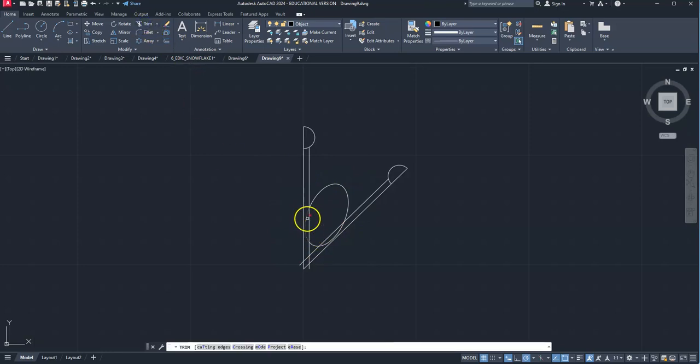So I'm going to trim these 3 extra parts of my ellipse because I only want that part that's connecting those 2 lines that I connected to. Now I'm going to offset this, O, enter, and I'm going to offset this 0.25. Now this is going to look significantly thicker than over here, but when this is arrayed, that 0.125 is going to be added to this 0.125 to create that 0.25. So now I'm going to trim these extra pieces.